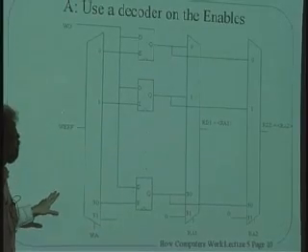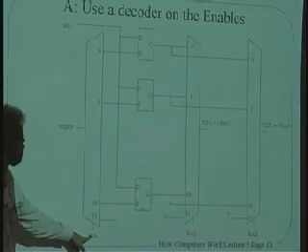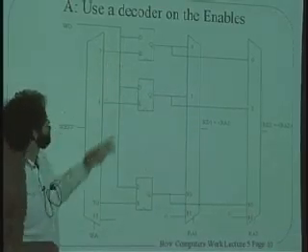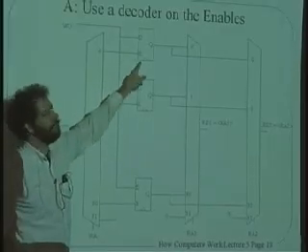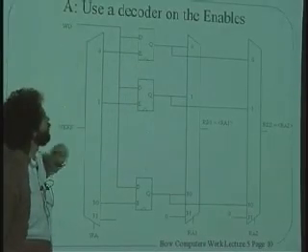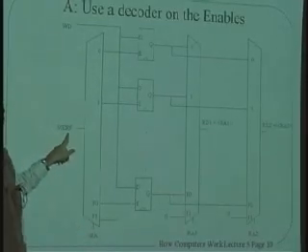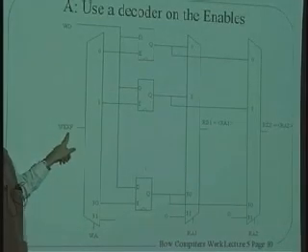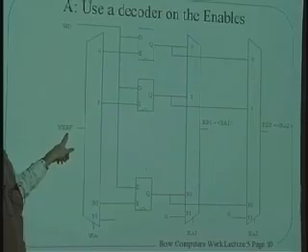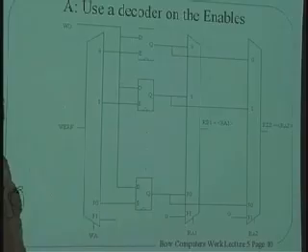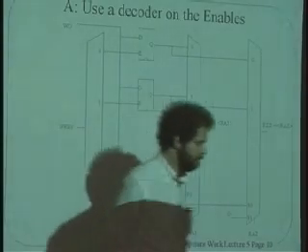And what that really means is, let's say we're writing to register number 0, and this wire is connected up to the 0 up here. It's saying, should register 0 pay attention to the data that comes in here when the clock goes off? And if WRF is 1, then the answer is yes. And if WRF is 0, then the answer is no. So it will not write something. It's just 1 bit, either 0 or 1. Okay, so that's the general idea.